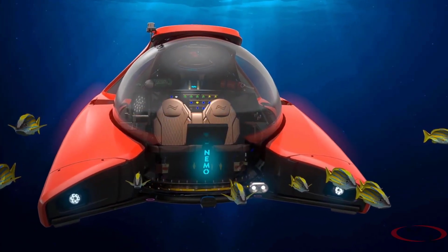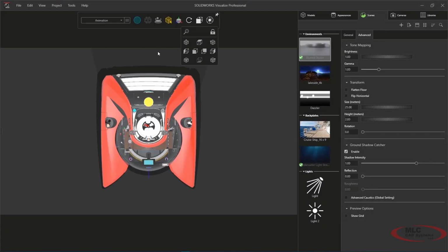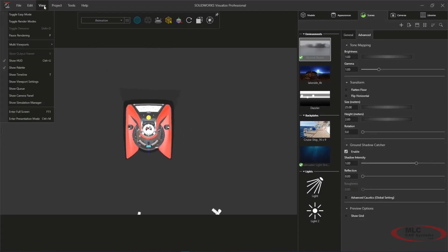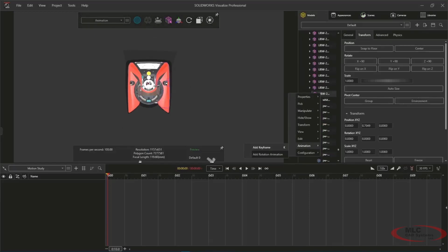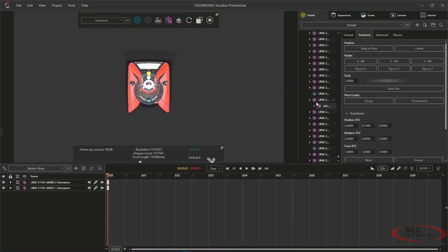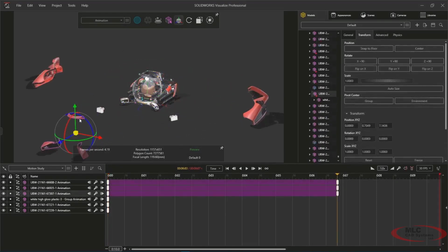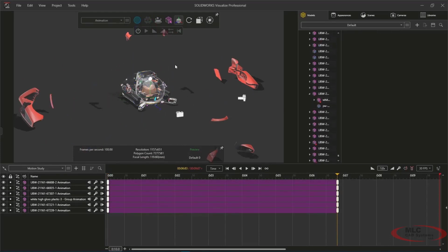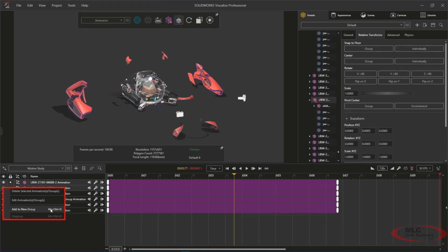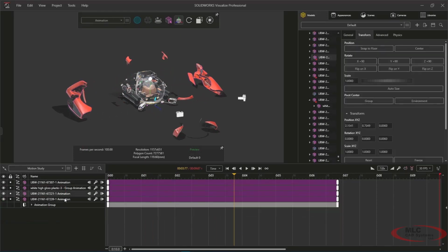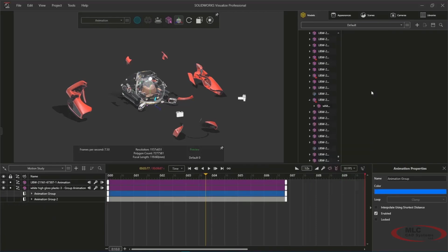For the final rendering, a third configuration is created to capture an exploded animation of the Nemo. With the timeline enabled, groups are selected and keyframed to define their start and end positions. Going through this process of keyframing multiple parts and groups can quickly clutter the timeline. Now in Visualize 2022, items added to the animation timeline can be nicely organized into folders using the group options. The animation ribbons can also be color-coded, making it easy to find and reposition these keyframes into the perfect place.